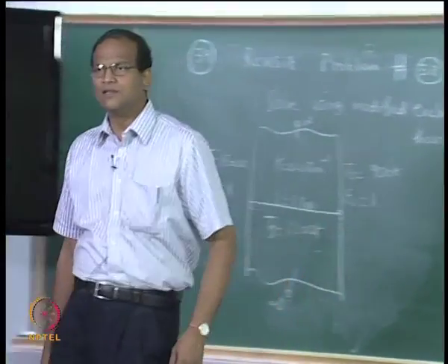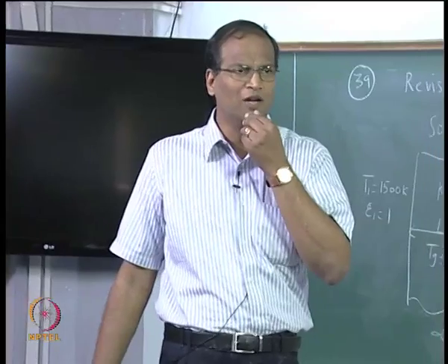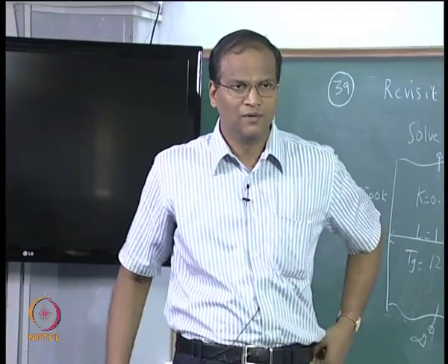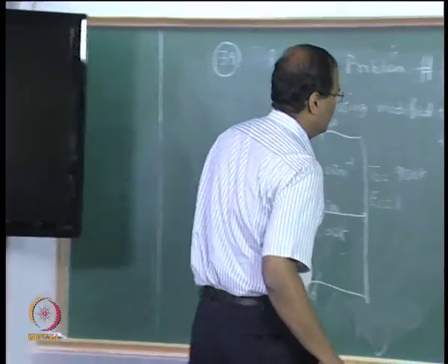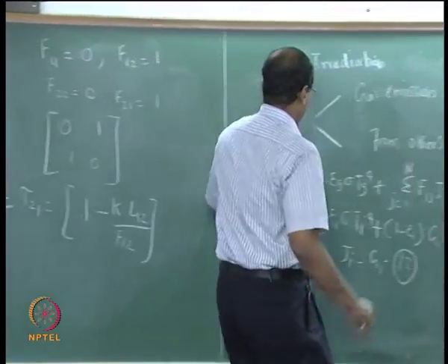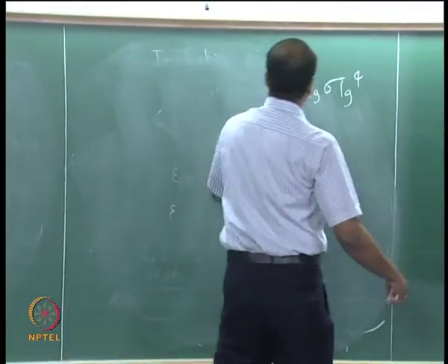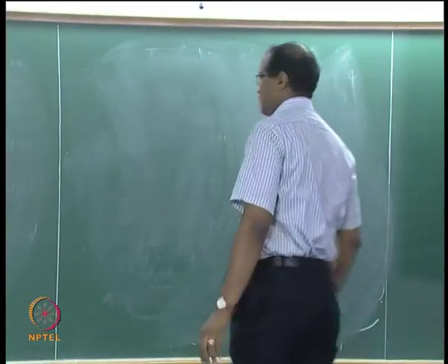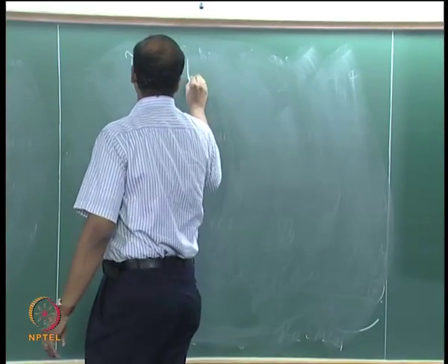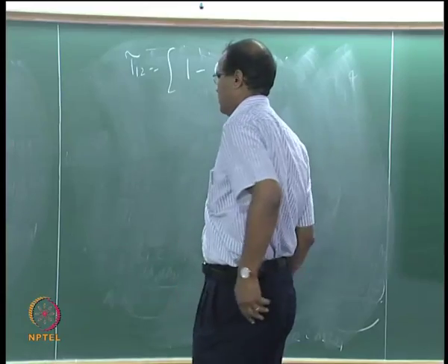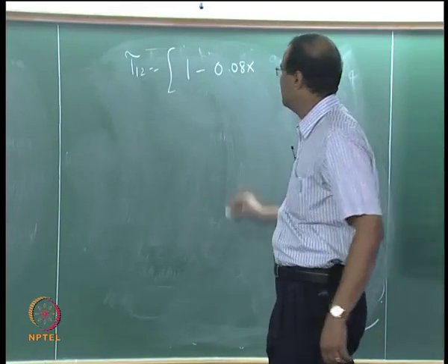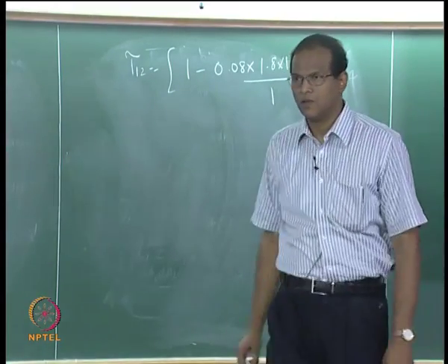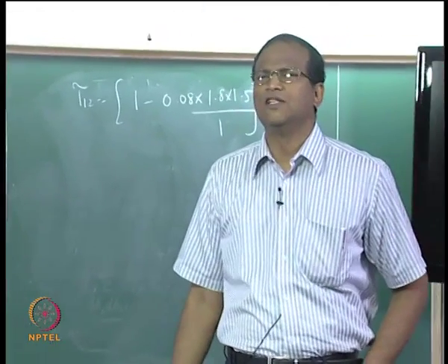What is L12 for parallel plates? 1.8. We will take the 1.8, or you want to take 2? 1.8 is given in the tables, we will take the 1.8, okay. What is L12 now? 1.8 into 0.784, huh?